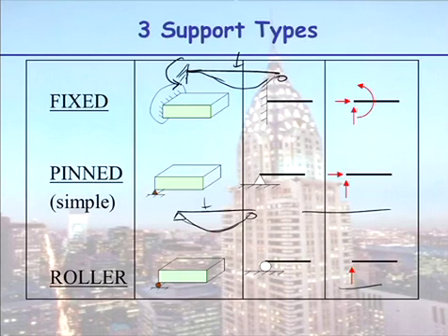So when we ask you for the reactions, we're not only asking you for force reactions, we're asking you for moment reactions as well. And you have to go, that's a fixed support, there's a moment reaction; pin support, only force reactions.